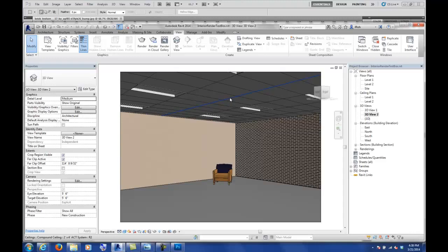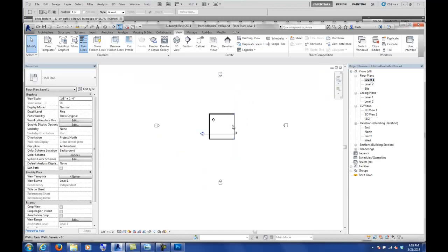So what I would suggest is you mimic the same thing. If you ever do the infinite plane in Rhino, all it's doing, if I go into a plan view, is zooming in, really, really far out, and making a big box that's a little bit lower, like a big floor. That's a little bit lower than the lowest point of your topography, so that you still get the rest of your topography. And when it drops off, if your topography extends far enough, it'll look like it's continuing on in the horizon. That's the best way to do it, to trick it.